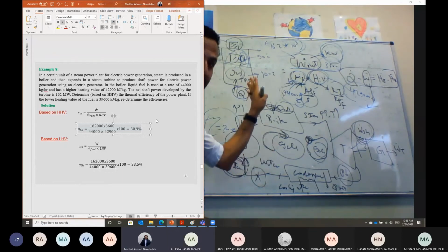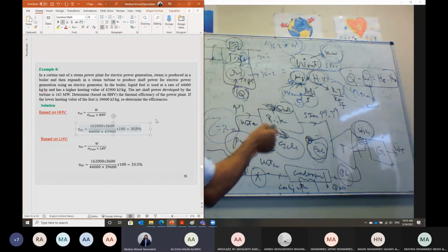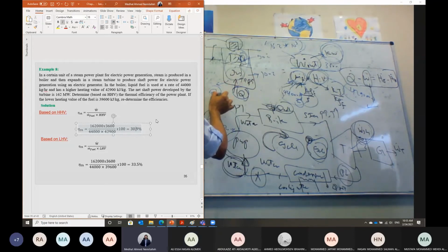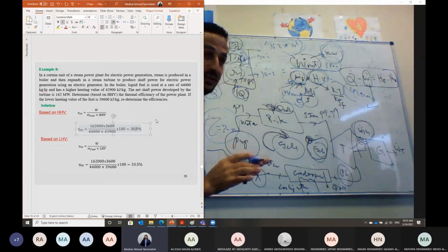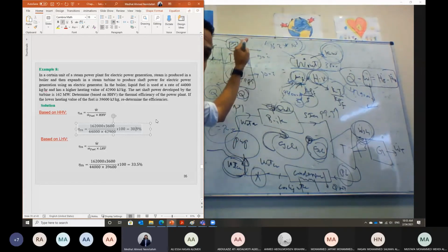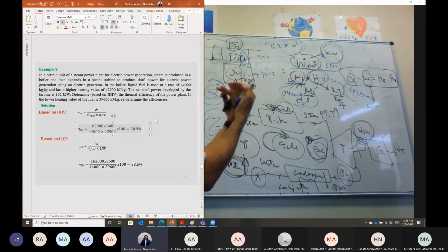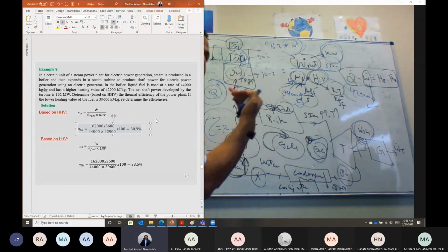We have heat right now. We need to lower the temperature. We need to lower the temperature, and that means we have to reject the heat here. But don't say I have heat and I need to use it. It's okay, if you want to keep this heat, just keep it. The piston will be up there and it will not get down. To repeat the cycle, we have to reject some heat. Then the gases will contract, and the piston will get back down. Then we can repeat it.